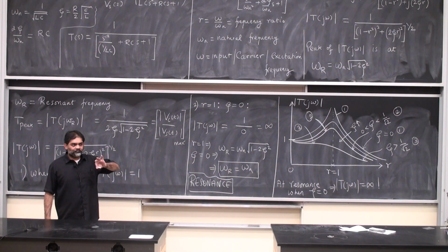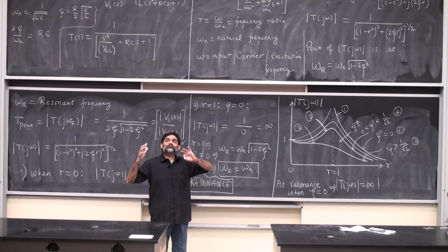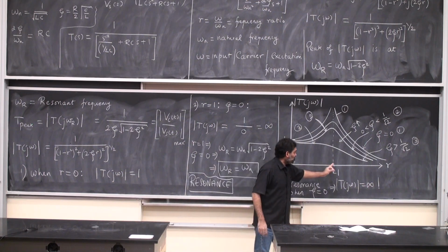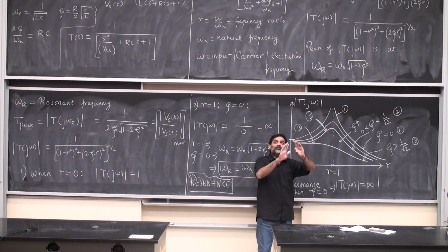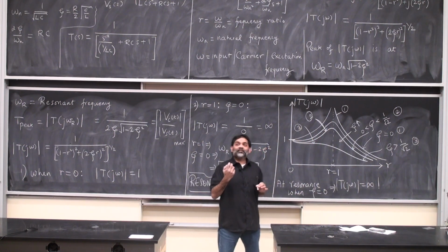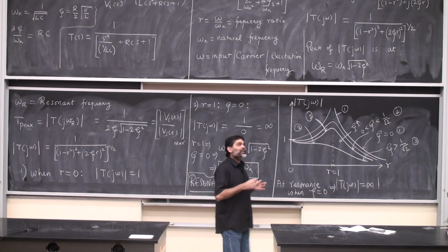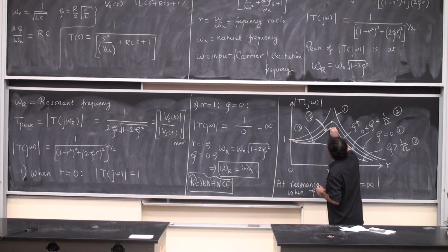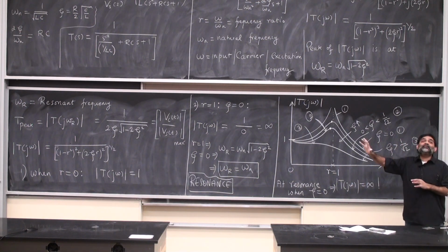Okay. So first thing is I have the first curve, which is when zeta is 0. And you can plot it and you can figure out there is something unphysical happening at the resonant frequency. The magnitude becomes infinite, which is why I don't join it. Okay. But then you see that as I start adding finite amounts of damping, you will see that the peak still occurs. But this peak value will keep shifting to the left.